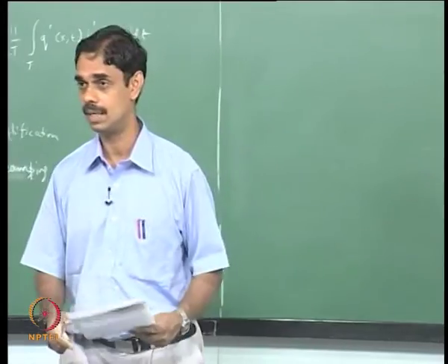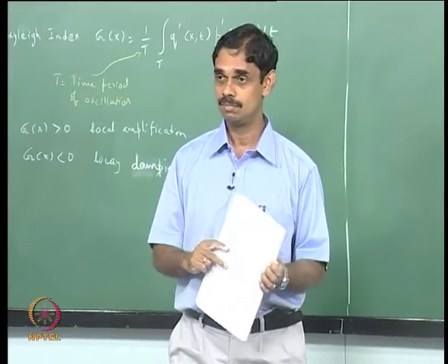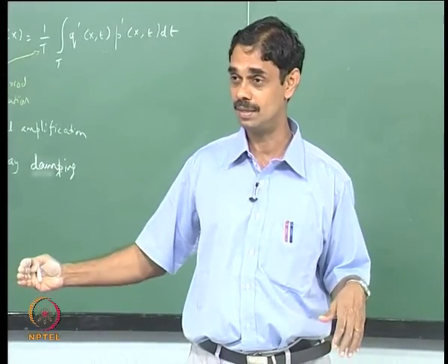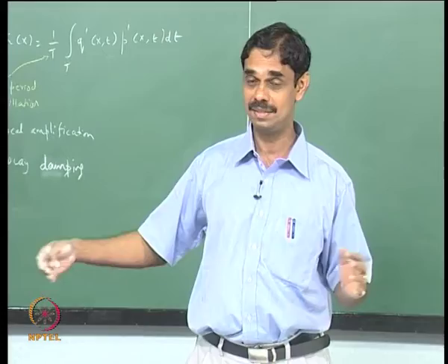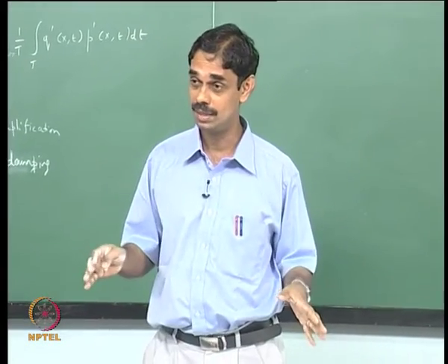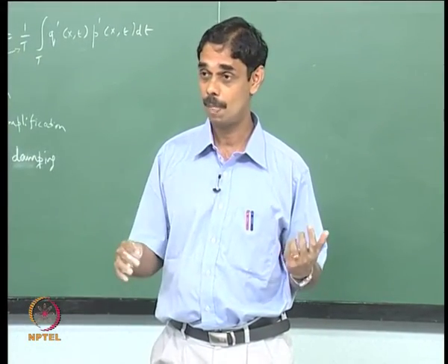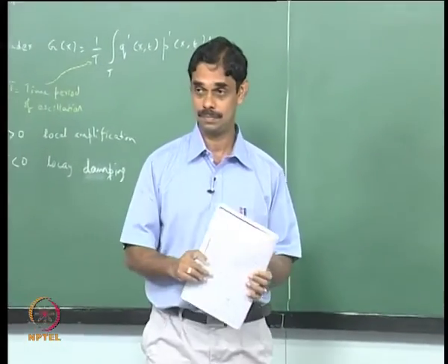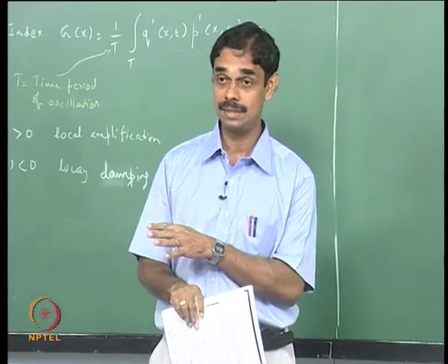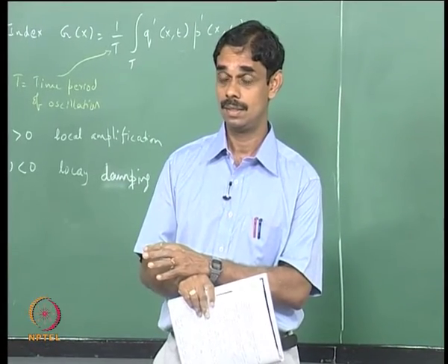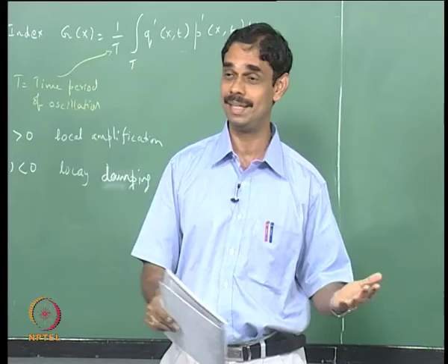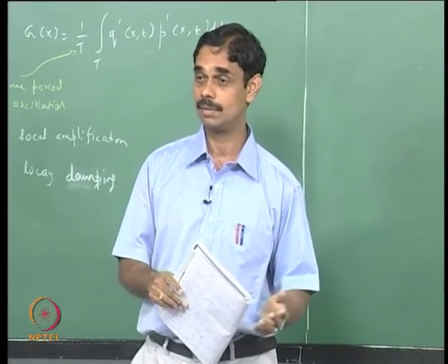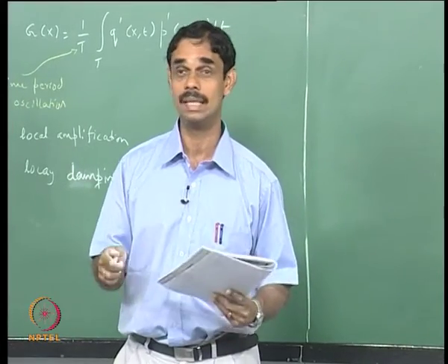It is the acoustic field in the duct, and so it critically depends on that. That gives the idea that, for example, if I found a system to be unstable for given boundary conditions, I can alter the boundary condition, and with the same tau time delay and all that, the system may become stable. That is actually the principle for active control, which we will see soon. If we can somehow adjust the phase between pressure and velocity, then we can make any system stable, which is the clue towards active control or anti-sound and so on. Very good question. Any other questions?